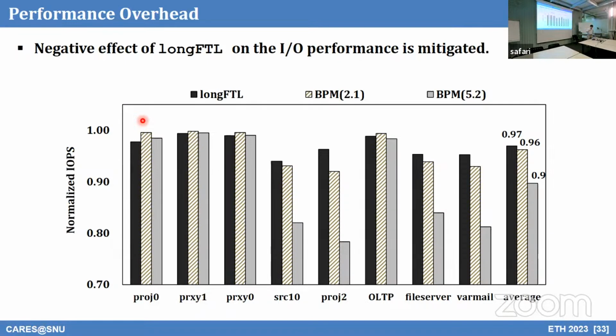Okay, the first question: actually, we are not spreading out the damage. We are making some room for weak word lines only. We apply low stress mode only to the weak word lines, not the strong word lines, which we don't care about.